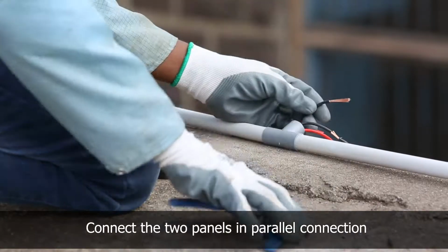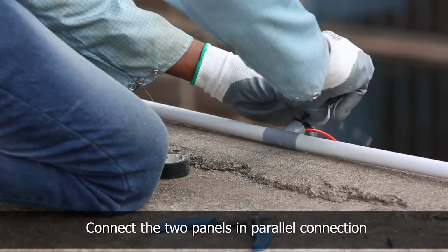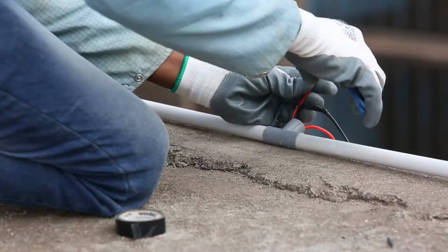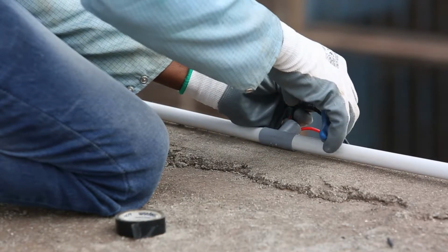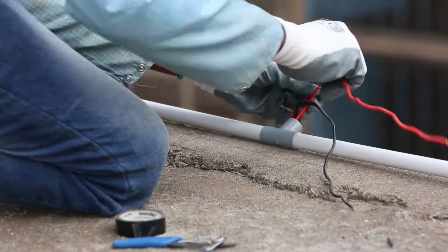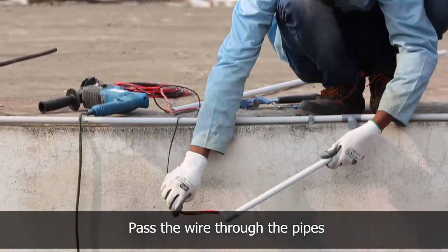Pass the positive and negative wire from both the panels through the PVC pipe. Strip the wires and connect both positive red and negative black wires of both the panels in parallel connection and pass it through the conduit.